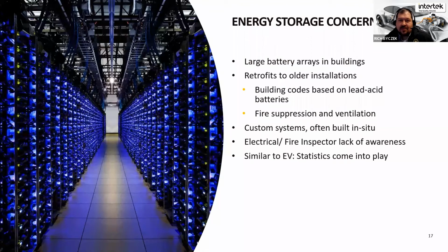And the hope is that the majority of those kind of failures are going to lead to a fairly benign event. The battery capacity is reduced, one module needs to be replaced. But on the other end of that, one of those single cell failures could cause the entire system to go into a propagation thermal runaway event, and you have a large scale fire that can't be effectively contained.